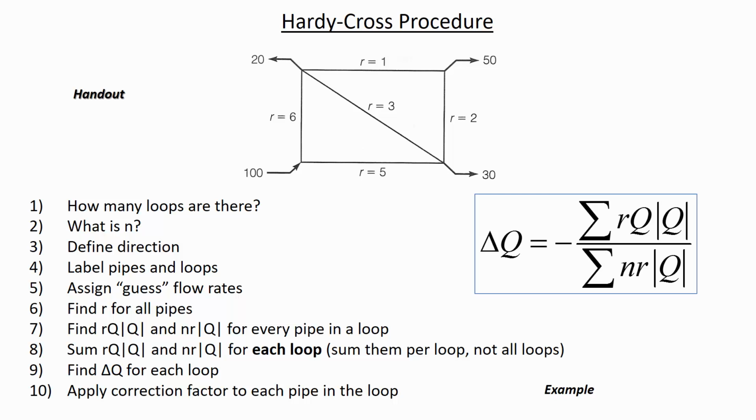And when I put the numbers into my method, if it was 10, I would put positive 10. But if I had flow going this way, that's against my positive direction of flow. Clockwise is positive, but this is going counterclockwise in the loop because this is positive.